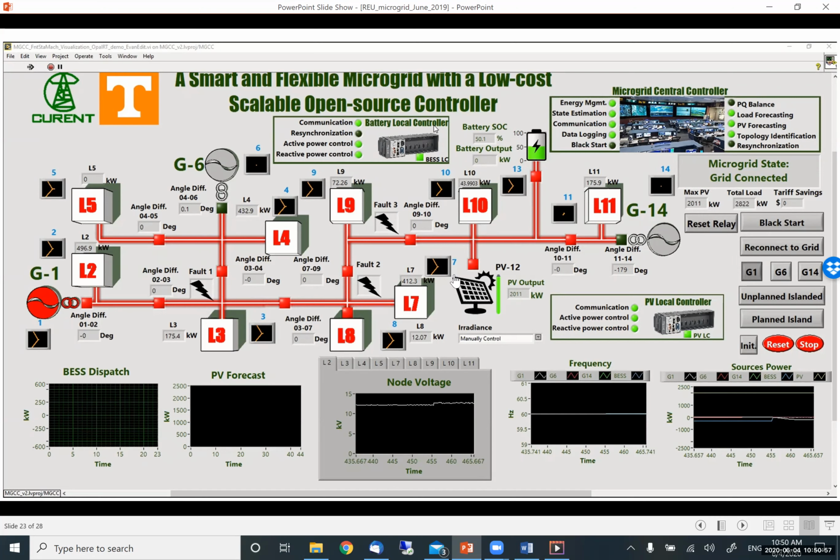And then we bring the PV in, and then we pick up one load section step by step, because every time you bring in either load or source, you introduce a disturbance to the system. We make sure the transients are gone, then we can pick up another section or another source. So this is a step-by-step process, starting from everything being in outage, everything disconnected. This process we call black start. Okay.